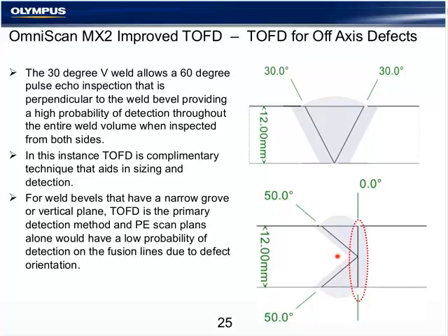Why use TOFD if you're using phased array? Improved length sizing, depth and height sizing, and improved detection of flaws that are not perpendicular to the weld bevel or to the beam of the probe.